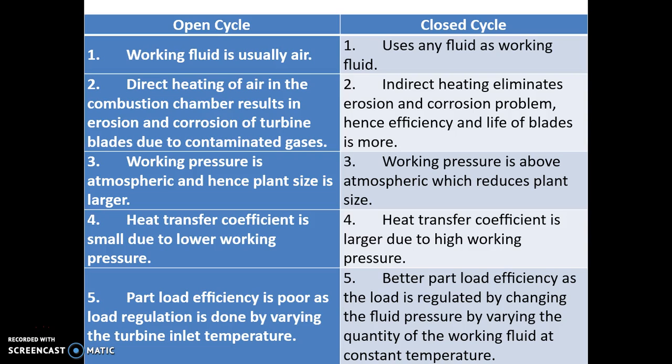The heat transfer is small in the open cycle, but in the closed cycle the heat transfer coefficient is larger because of the high working pressure. And in the open cycle the part load efficiency is poor because the complete cycle is regulated by the flow of the fuel. But in the closed cycle we can have a better efficiency when the engine is partly loaded, and that is by controlling the fluid pressure.